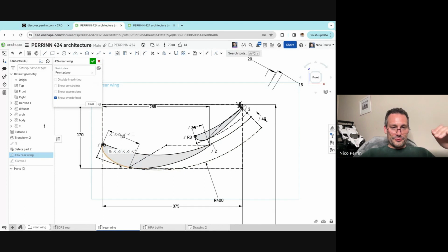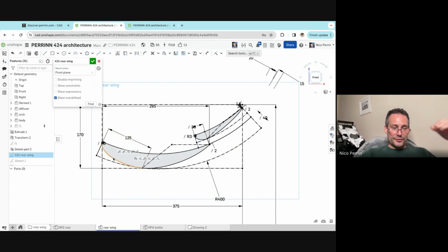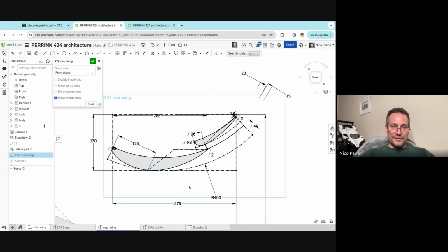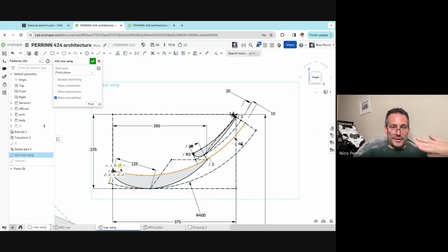Here you've got the description of the leading edge. That 90 mil is quite important. I could maybe increase that to 125. Now you've got a more progressive acceleration of the flow under the wing. And obviously, if I wanted to increase downforce, typically here, I would basically make the box bigger. So I would increase the expansion of the wing. So here is 170. I could go to 225. Boom. You see how the wing is much more pronounced. That would be a very high downforce one, maybe even separating.